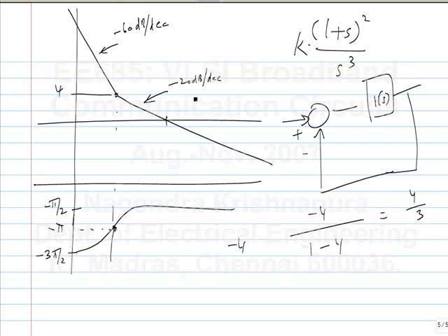Is this part clear? So you can have gain more than 1 and a phase shift of pi. Although it looks like the feedback is adding up in phase and larger in magnitude, it doesn't blow up. This happens particularly with conditionally stable systems. If you plot the root locus of this and reduce the value of k, meaning I shift the entire magnitude plot downwards, this becomes an unstable system.